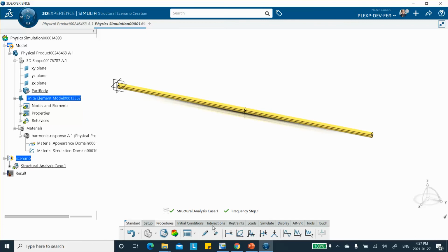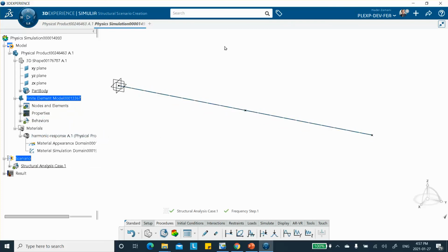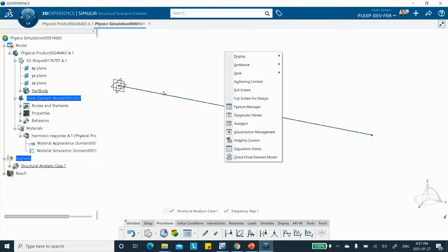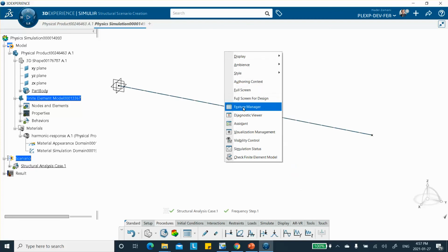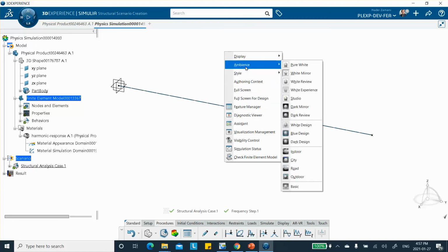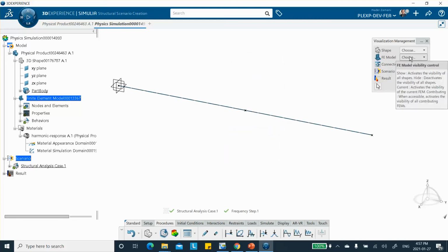And now we're going to do the restraints. But first of all, if these things are bothering me in order to pick the lines and things like that, so let me do the following. I'm going to hide the section properties. I'm going to hide it. Right click, hide, and I'm going to hide the elements, by the way. So hide the elements. The elements hidden.